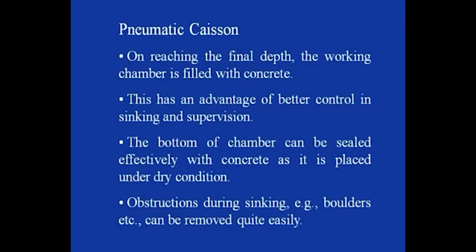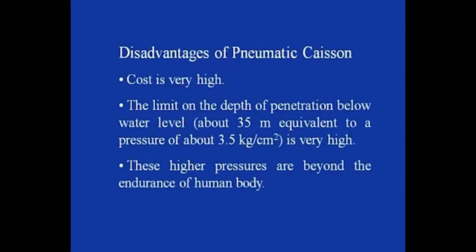Obstructions during sinking, for example boulders, can be removed quite easily because the excavation takes place under very high pressure. Some of the disadvantages involved with pneumatic caisson is that its cost is very high as compared to open well and box well.